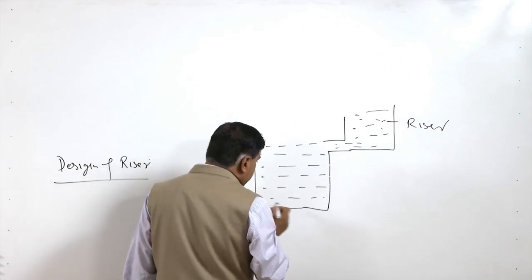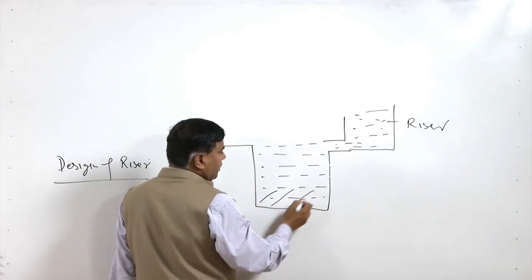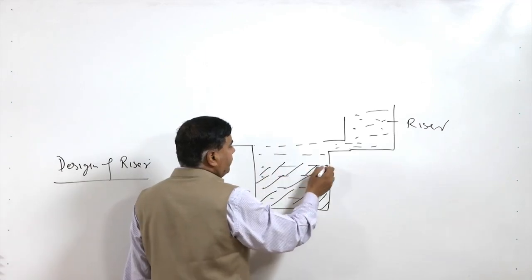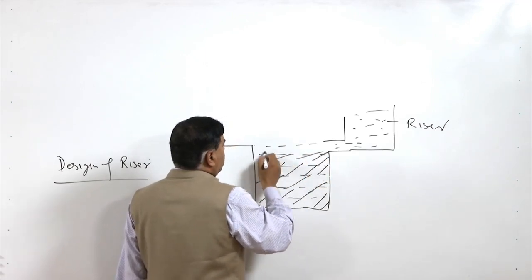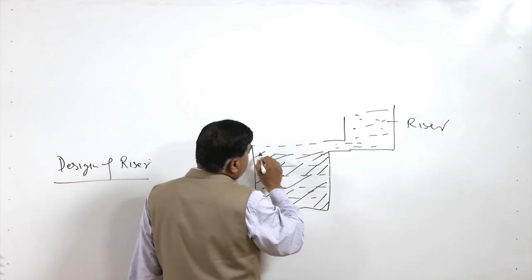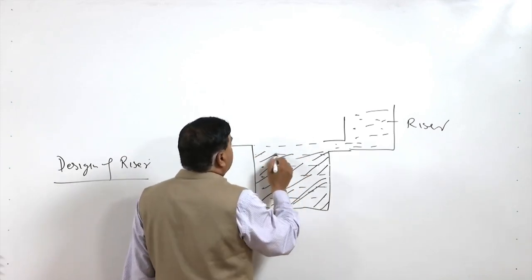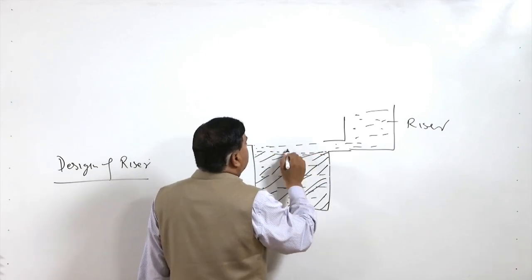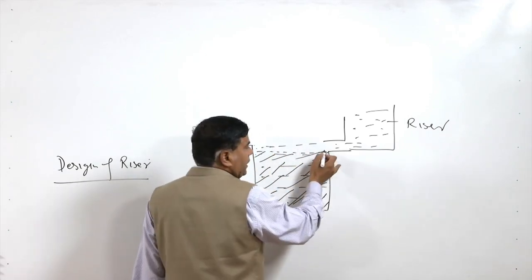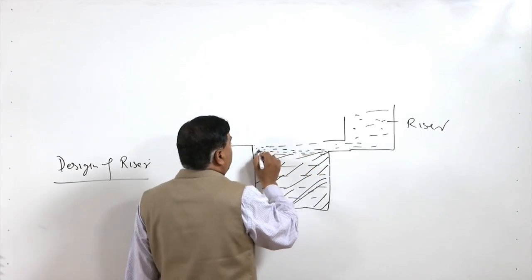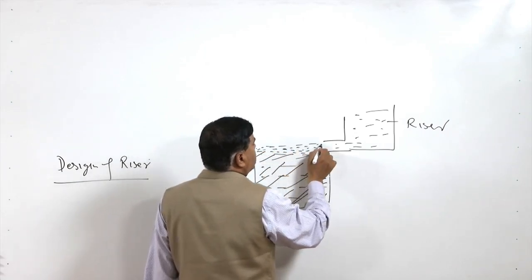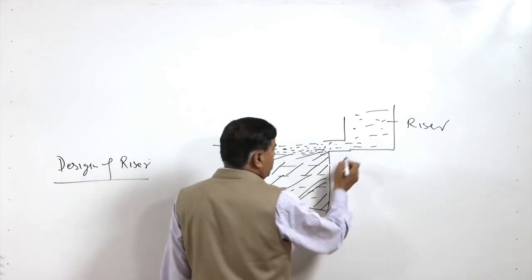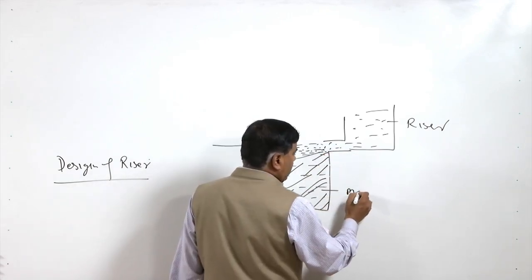It is expected that the solidification of the molten metal will take place first in the mold. Once this solidification is over, whatever shrinkage due to this transformation has occurred will be left at the top. That volume of the metal which is deficient due to the shrinkage is to be fed from the riser.